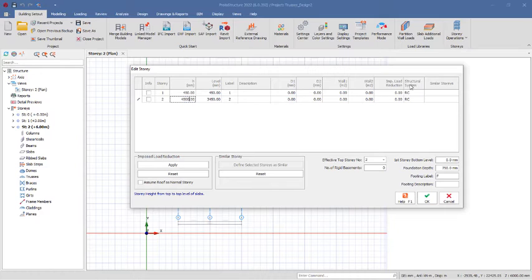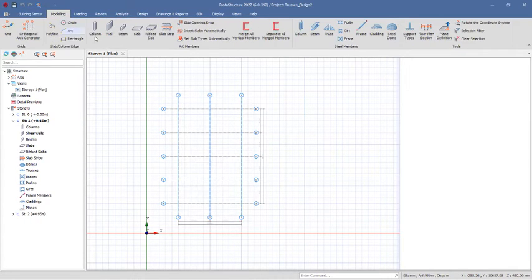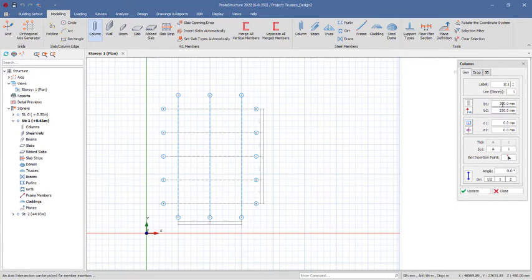Okay, so come to the structural system, very important. At the foundation, we have it to be concrete. At the substructure, the superstructure, we have this to be steel. So click on OK. Alright, navigate to story 1. Then go to the modeling tab, click on the column. So we are going to be inserting a column of length altogether to be 1200 from the DPC to the foundations level.